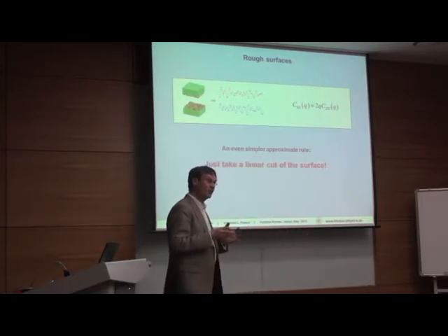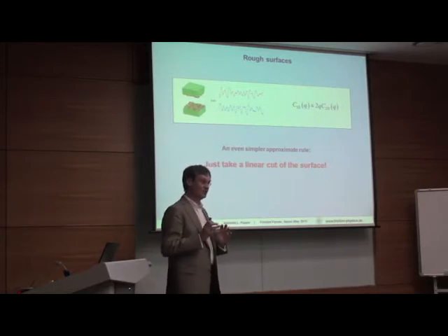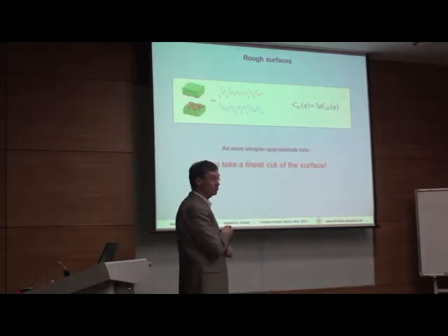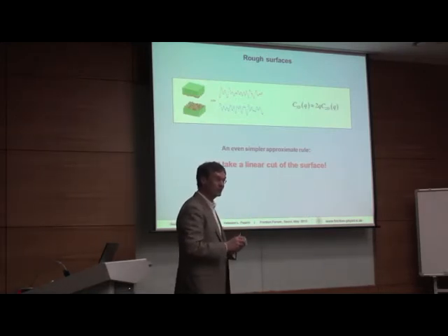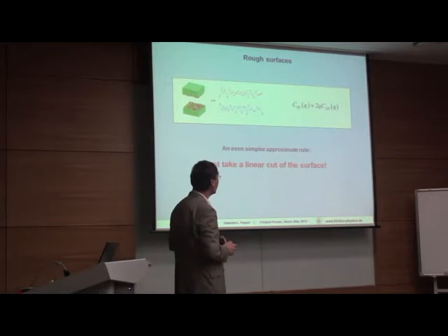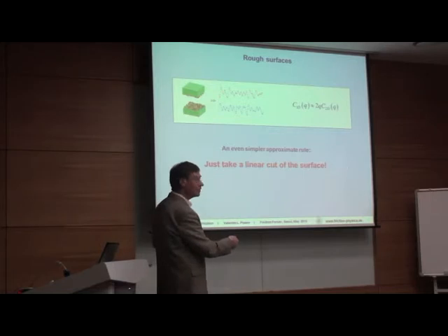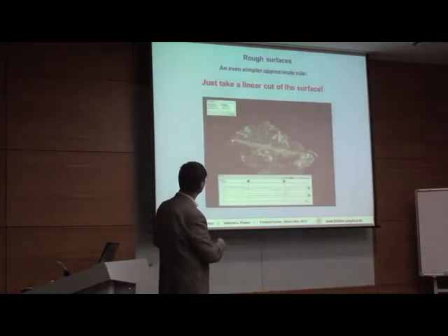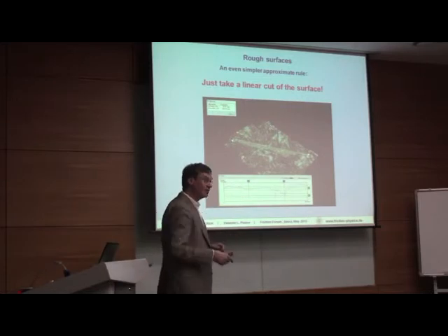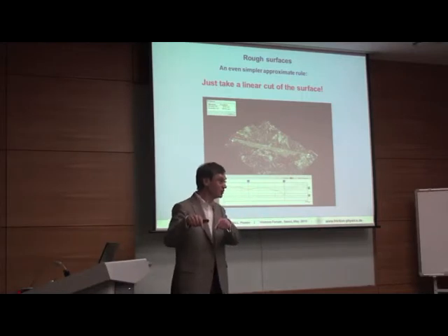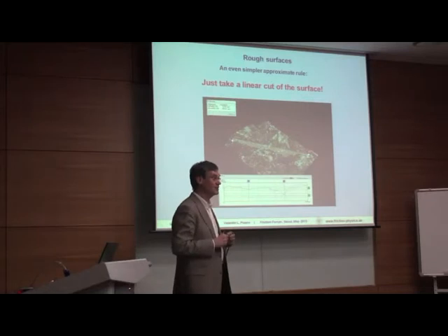But for typical Hurst exponents, typical self-affine surfaces with Hurst exponent about 0.5 to 0.8, it is just multiplying with the wave vector and 2, and it is okay. In the same interval, it is really a simple rule. You take the two-dimensional surface, make a one-dimensional cut, and this cut has the spectral density 2q times C2D, so it is already the substitute surface.